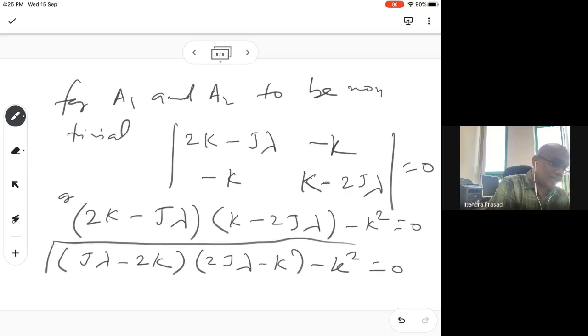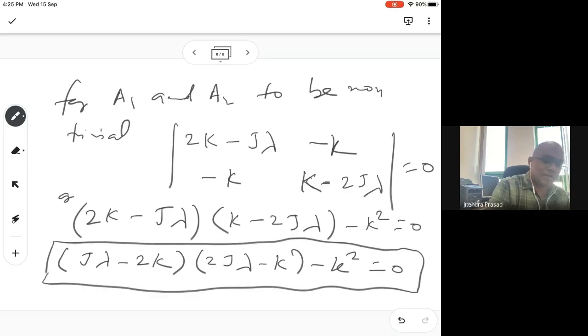So we have this equation. We can solve and find out omega, which will be the natural frequency. Since the number of degrees of freedom here is 2, it will have 2 natural frequencies, and those will be found by solving this one. Lambda equal to omega square, so omega n will be equal to root lambda. There will be 2 lambdas, so there are 2 natural frequencies.